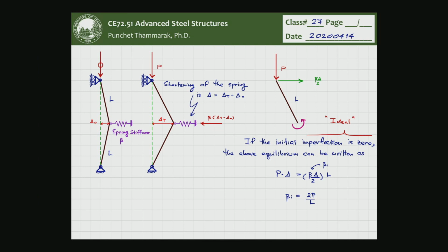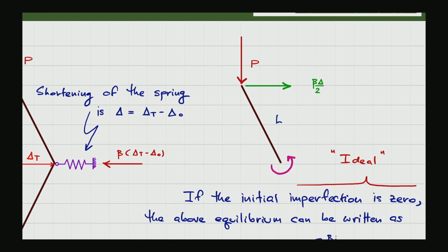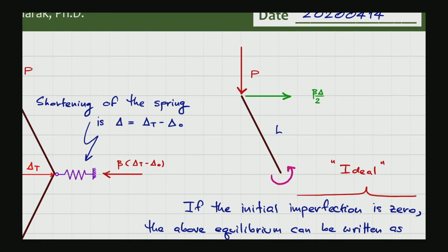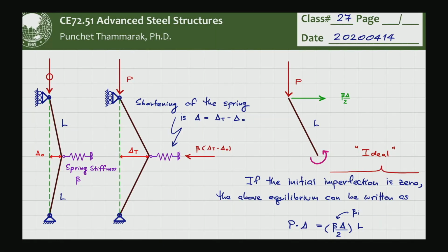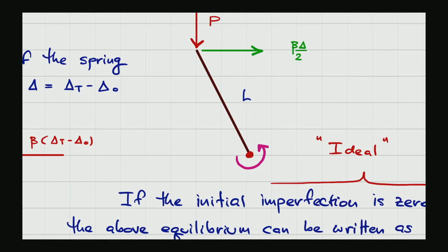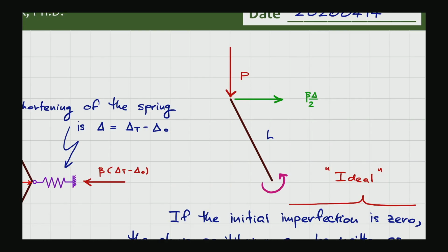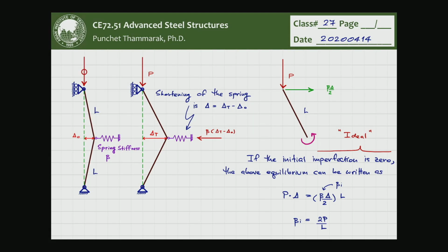So first of all, the ideal brace stiffness is revisited. This is the top piece of the column, and as you have learned, the concept of the fictitious hinge was adopted in the previous paper by Winter, so it is possible to cast the equilibrium equation of this upper piece of the column using just the axial force applied and the horizontal force which comes from the support.